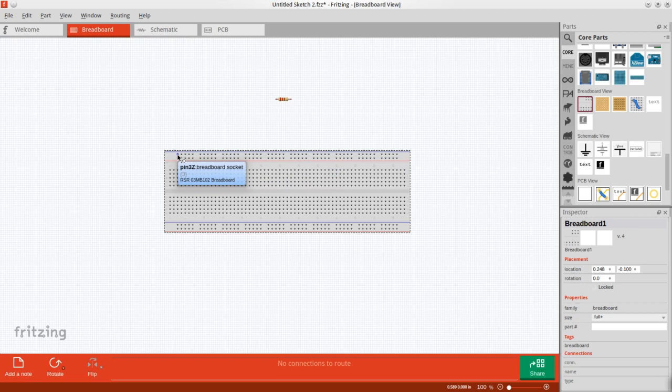Now, what's nice about this program is you just click on a hole like this and it will pull a wire magically out of the hole. Of course, that doesn't really work with a real protoboard, but in this case it does. So I just pulled a wire out and connected up the long row on the top with the long row on the bottom that's next to the blue stripes. Now if I click on any one of these holes, they all turn yellow on both of them. That indicates that they're electrically connected.